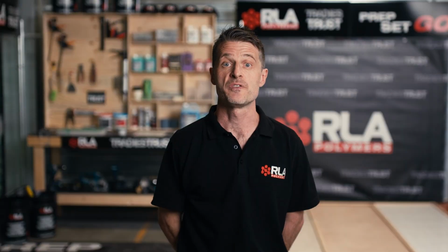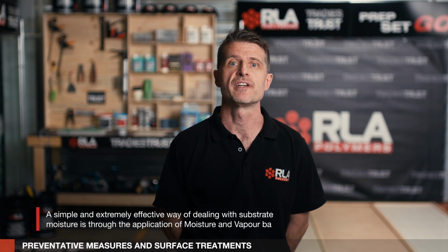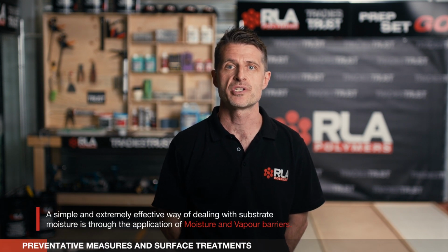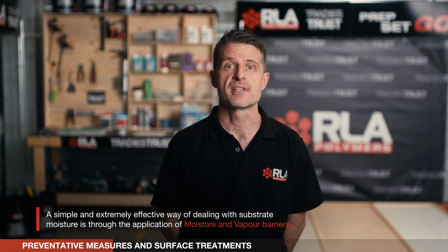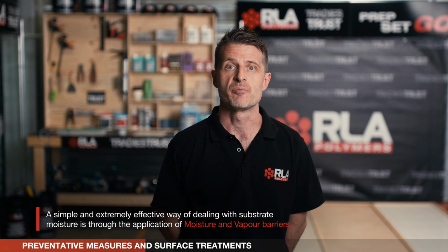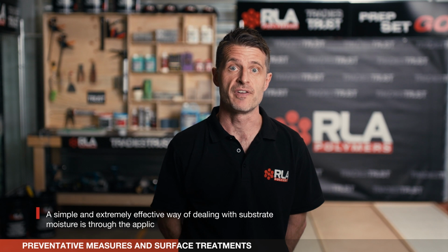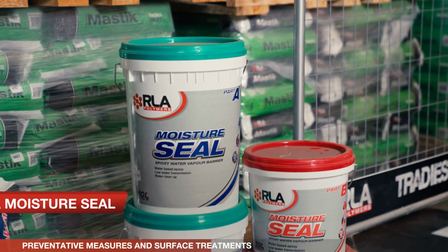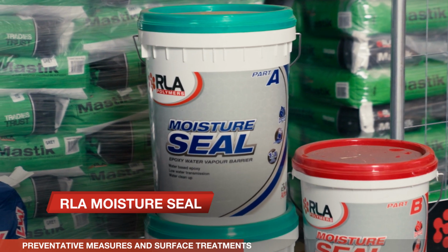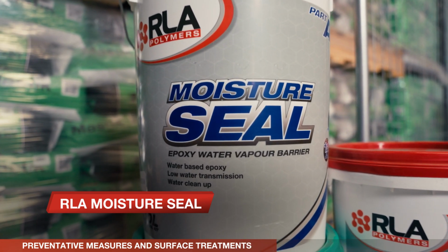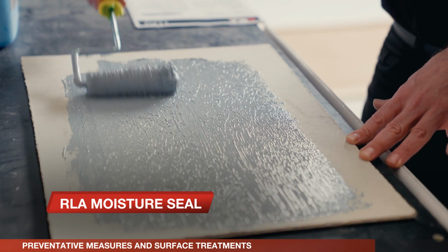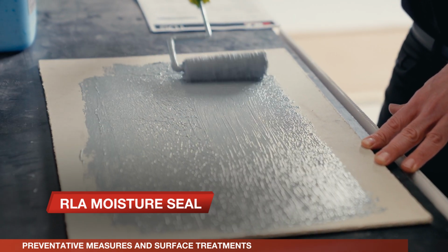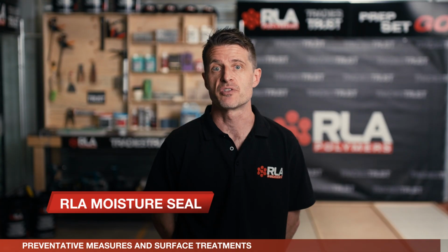Now, surface treatments. A simple and extremely effective way of dealing with excessive substrate moisture is through the application of a moisture or vapor barrier. Now, these are surface treatments that have been around for a long time and have a proven track record in negating the destructive effects of excessive moisture. So RLA Moisture Seal is one such example, and it's a water-based 2-part liquid epoxy coating that cures to form a hard-wearing, high-bonding protective coating that is able to suppress active moisture whilst drastically lowering vapor transmission rates to acceptable levels. Applied in 1 to 2 coats to a surface, it can be finished directly over with a range of coatings, adhesives and finishes.